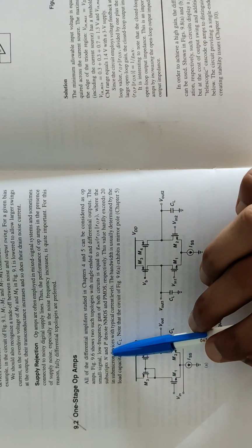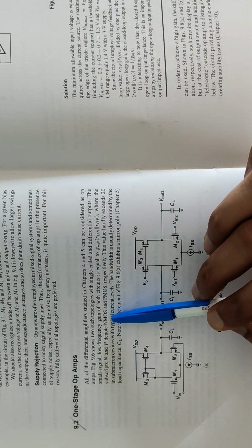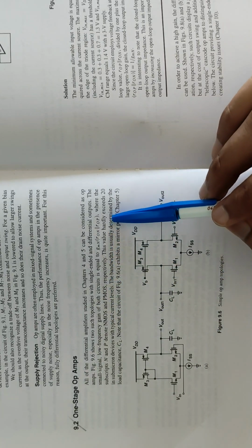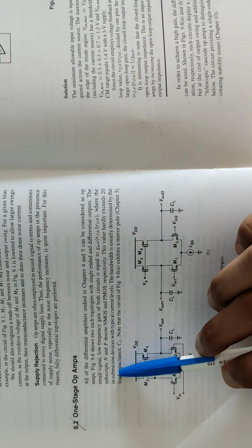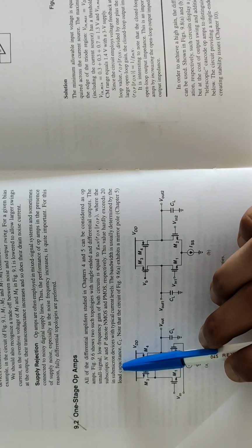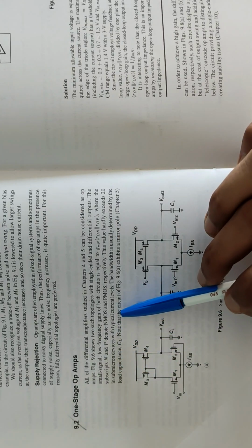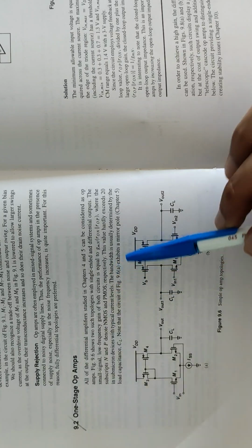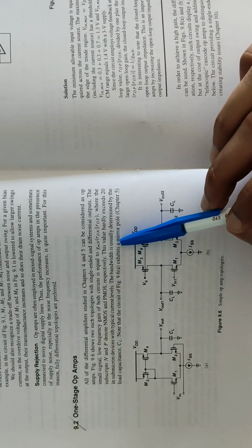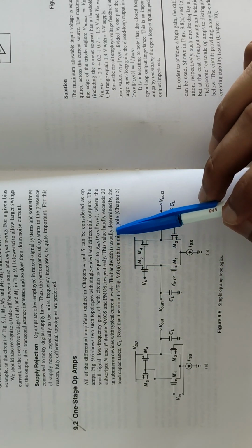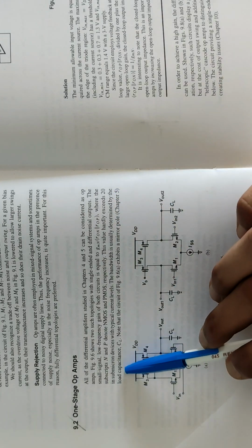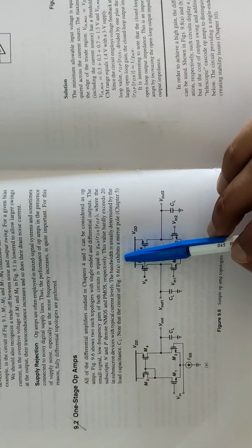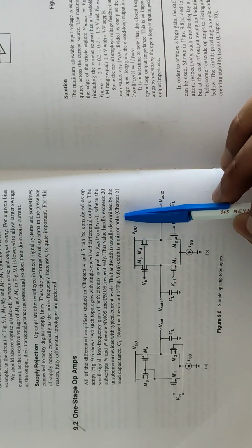The small-signal low-frequency gain of both circuits is equal to gmN (rON parallel rOP), where the subscripts N and P denote NMOS and PMOS respectively. This value hardly exceeds 20 in submicron devices with typical current levels. The bandwidth is usually determined by the load capacitance CL. Note that the circuit of figure A exhibits a mirror pole.